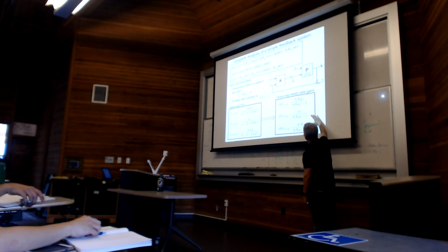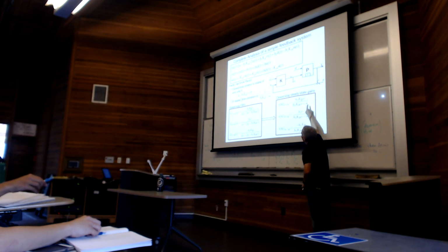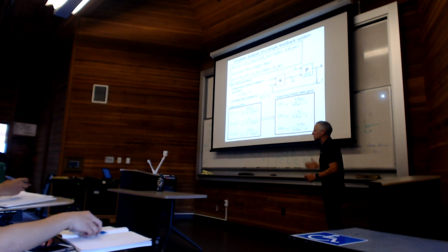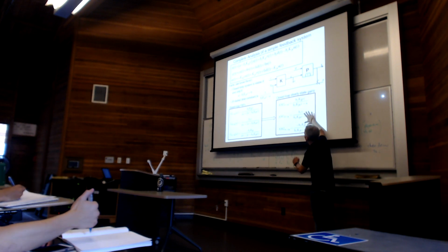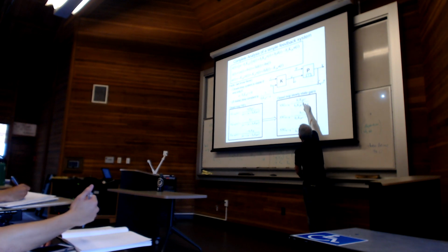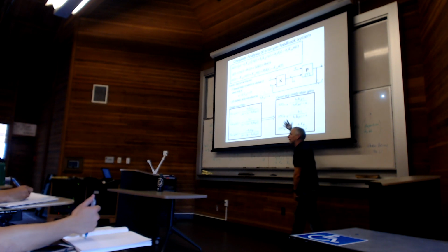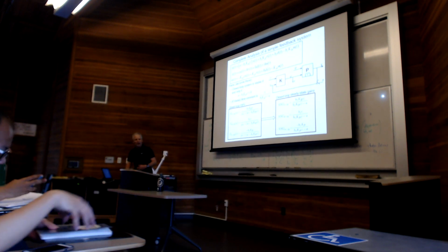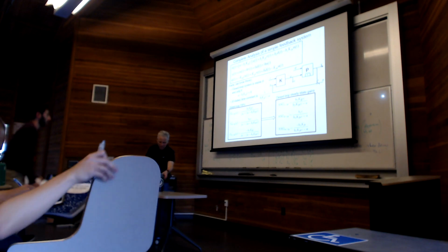Once KFB is chosen, what would I pick KFF to make the steady state gain from r to y equal to? 1, for instance. Then we know I'll get perfect tracking because no disturbance. So there's one way in which you could choose things. Pick this to get the disturbance attenuation you want, and then pick that to get r to y to be what we want. We'll play with these. I have lots of simulation examples posted for you, and we'll pick up with this next time.